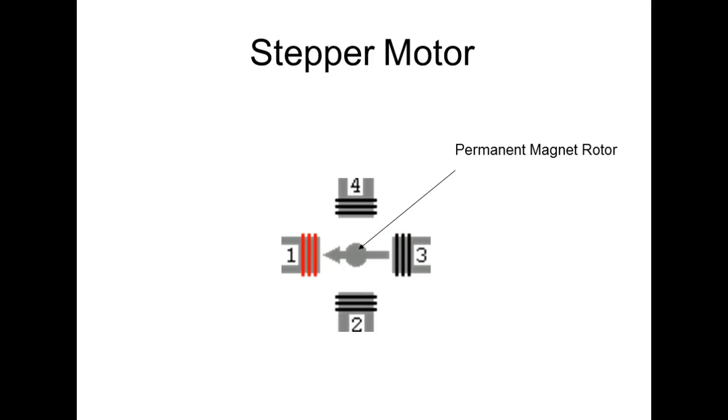But you got to understand, I can keep putting multiple poles in there. The closer I make the poles, the more precise the steps are. So I think the stepping motors that I'll show you are 24-step motors. So that's 15 degrees per step. So they have a very low rate of revolution. You can get these things up to 1,024 steps per revolution, so your degrees per step would be extremely small.